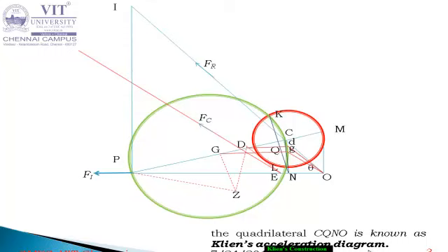Perpendicular to this Fc, we have to draw one more line which should meet the point I. We don't know the magnitude, only directions we have calculated. Theoretically you can calculate based on the value of m or omega square, but practically how can you find that value? Extend and draw one perpendicular line which should pass through I, so you can have the value. That should be taken as x. Clear? So that angle should be a right angle.